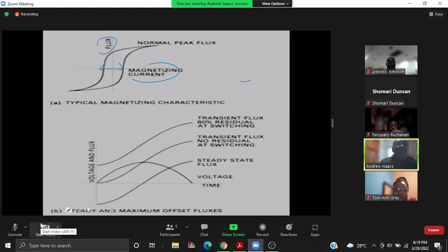But anyway, the bottom line is, in the cycle of magnetism, you magnetize by increasing the current, and you saturate here. Then you reverse the current. And this now gives you the width, therefore gives you the amount of residual flux.